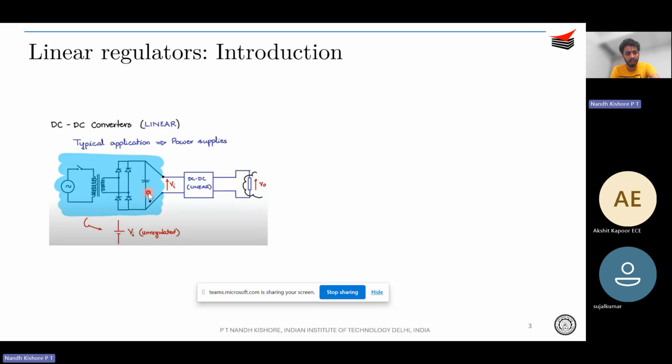You also saw that the relay and contactor mechanism was the best amongst them all, because it gives resistive inrush current limiting at the start, and as the capacitor gets charged up, the resistor is bypassed using a relay and contactor mechanism.